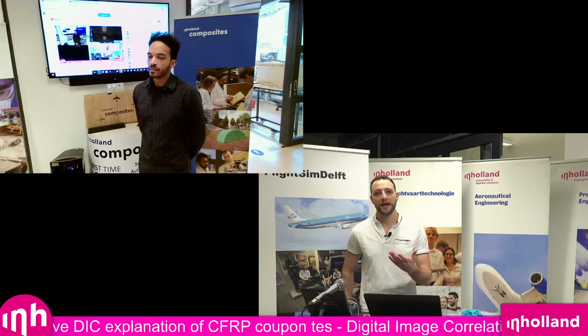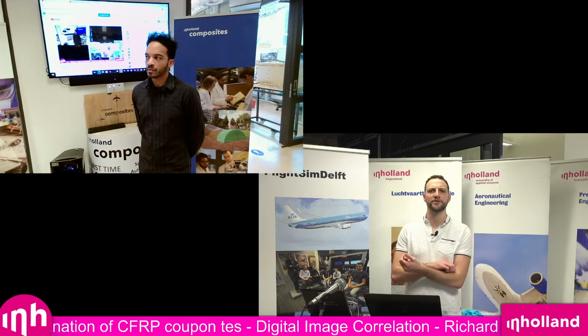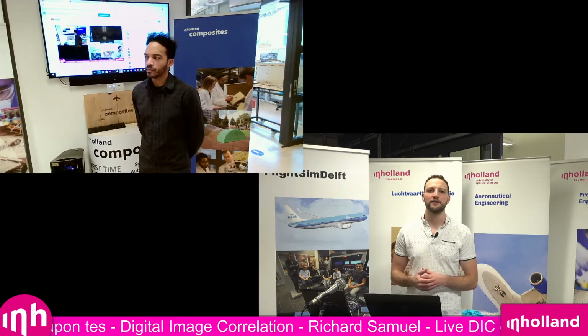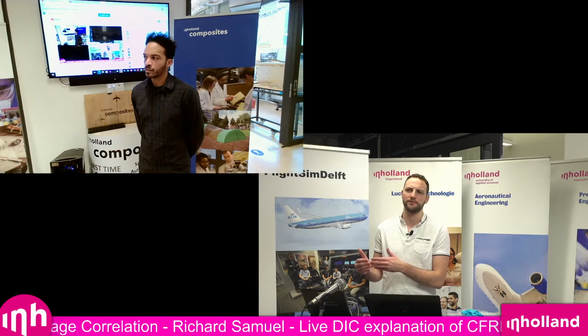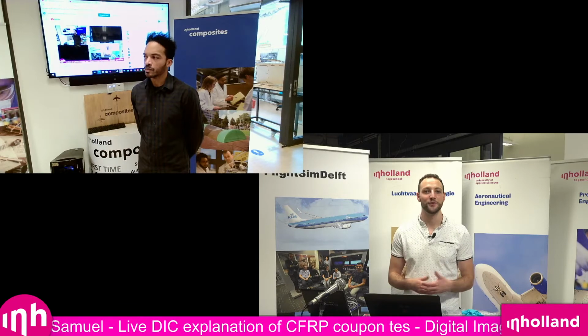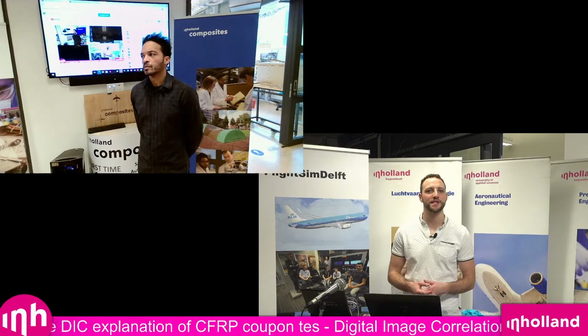But it is surprising how accurate the system can get just using pixel tracking, because 1 pixel for this camera is 3.45 micrometers, and we are tracking strain percentages with a difference of, I think, 0.032%. We are essentially tracking sub-pixels. So it is quite impressive for just using a simple 5 megapixel camera running at 3 frames per second.